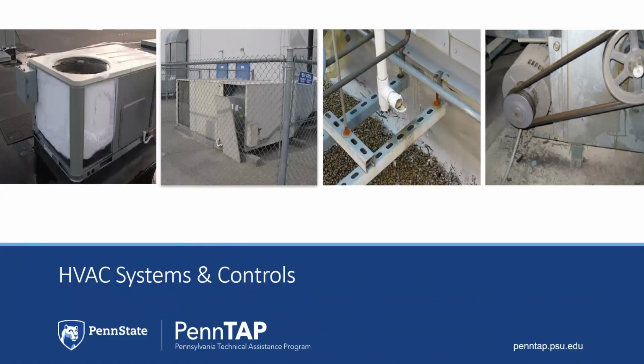Common problems are jammed or frozen outdoor air dampers, missing or damaged panels, seals, ductwork, non-functioning actuators or disconnected wires, malfunctioning outdoor air or indoor air return sensors. There could be faulty control settings, or it may have been installed wrong or wired incorrectly. Also consider any debris or plant life growing around your HVACs. In the photos, we have a seized HVAC. The faulty controls can be seen in this example, and the HVAC has physically frozen over.